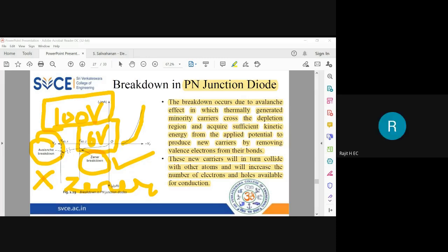Yes. So for Zener breakdown to happen, the junction diode needs to be heavily doped, right? Yes. So once I achieve the Zener breakdown, if I keep increasing the voltage value, like when you keep turning the knob, the current flow will keep on increasing. Will it ever change? Like, will it go past the Zener breakdown voltage even after that? No. After breakdown happens, the diode will work like a constant voltage source. So the voltage across the diode will be constant, even if I keep increasing current flow through it.